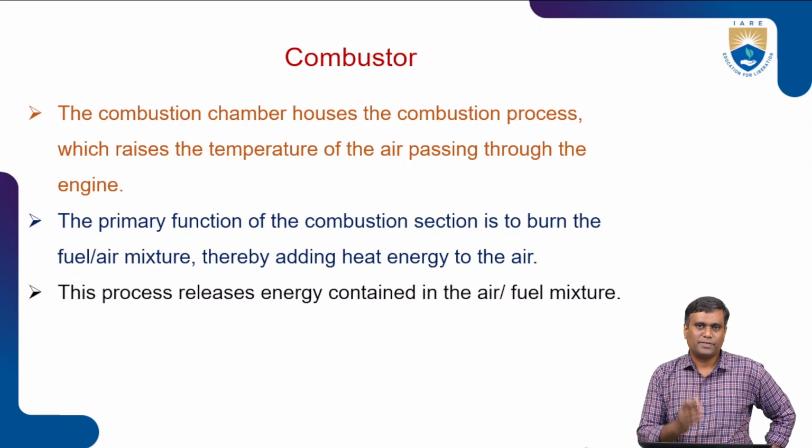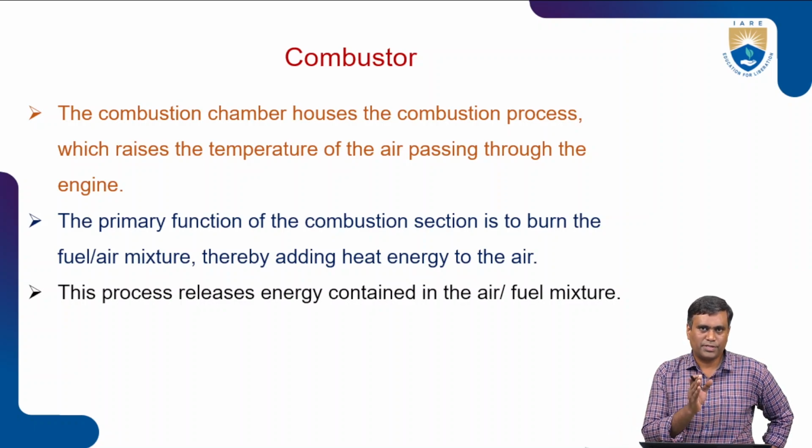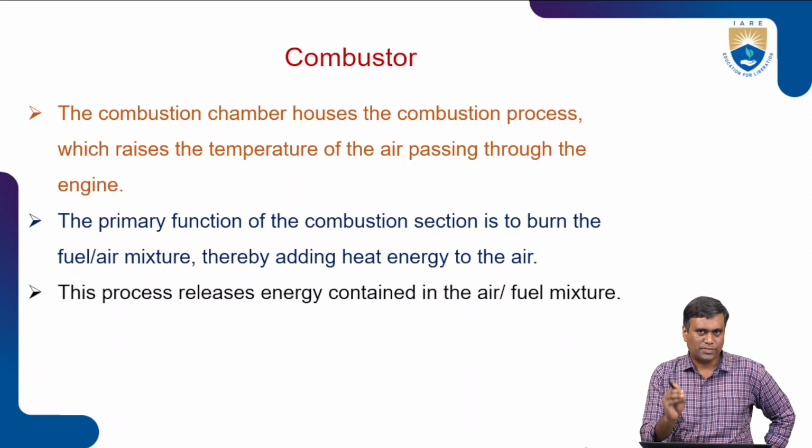The purpose of the diffuser is this: if high pressure and high velocity air is pumped into the combustor, where fuel will be added to it and combustion takes place, then due to these high pressures as well as high velocities, improper flame or improper combustion would be expected. Otherwise it results in improper combustion, which leads to inefficiency of the engine.